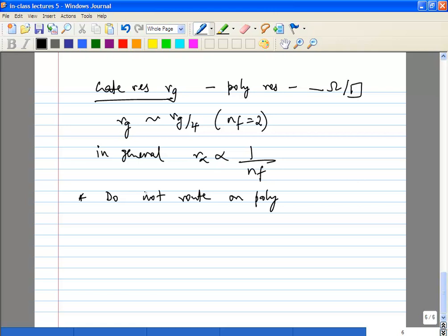There are certain cases where people do poly connections, and those are done for standard cell gates. For example, if somebody is building an ASIC and they want to do an auto place and route involving millions of gates, each gate should be laid out as efficiently as possible. Once you have thousands of gates, timing and other things become limited by the number of gates rather than the delay of each gate.